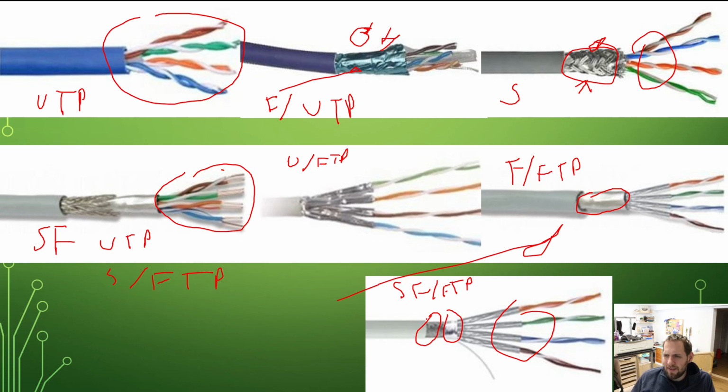So that kind of shows you all the different differences. And unless you're in an industrial environment, everyone's going to be different, and every cable location is going to be different too. It matters if you run this cable over a 4 horsepower induction motor, or if you run it 20 feet away from that motor. That will make a big difference.